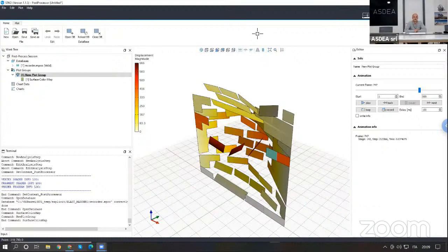If you model the nonlinearity, it depends, because sometimes you model the complete nonlinearity, like large deformation, contact, friction, plasticity, cracking. Sometimes you only model some of them. So it's up to you. You have to find out what value of damping you need to apply on nonlinear elements, depending on how much nonlinearity you have physically modeled.